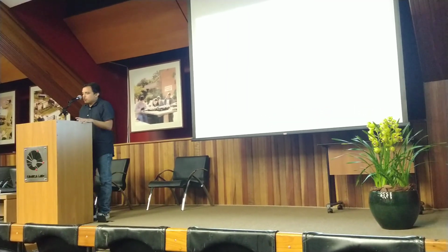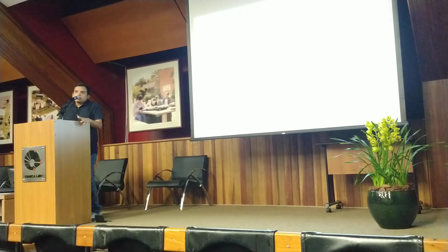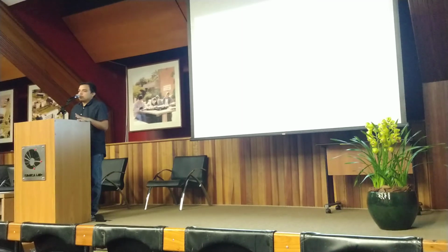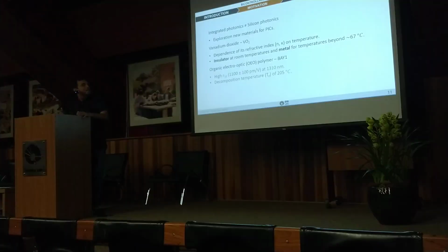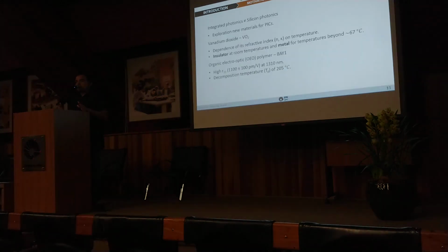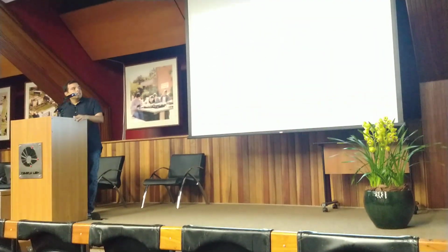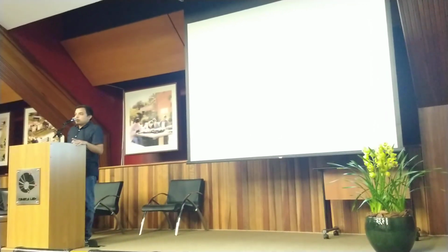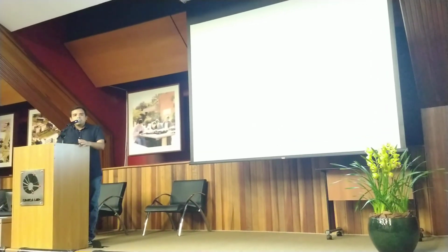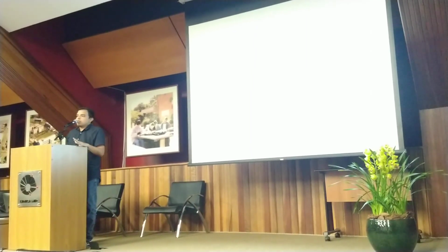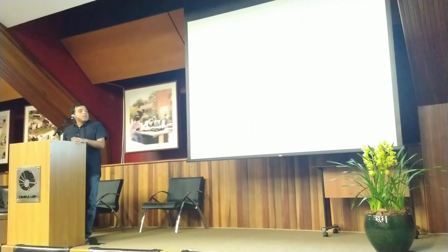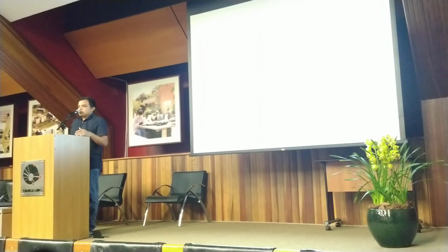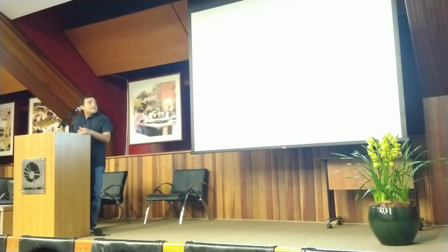The second material that I want to introduce is a polymer. In 2021, there was a recent polymer with a really high electro-optic coefficient, called BAY1. This material has around 1,100 picometers per volt at 1.31 micrometers. Another feature of the material is a decomposition temperature around 205 degrees. So with these two materials, with these two approaches, I propose this bicontrollable waveguide.